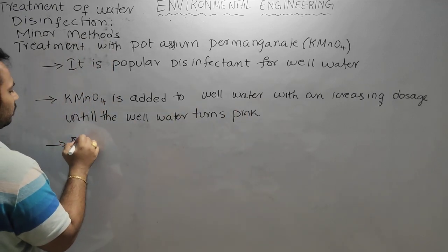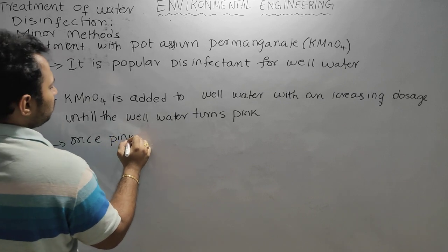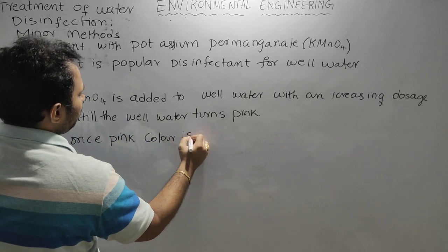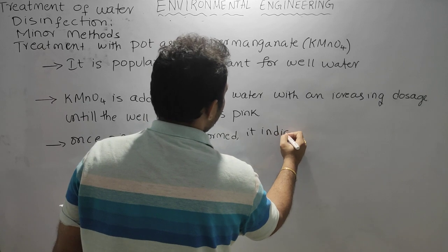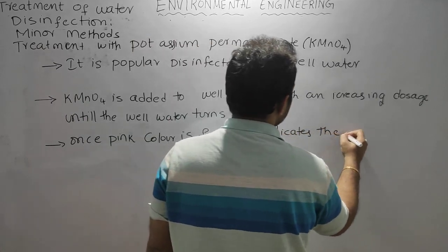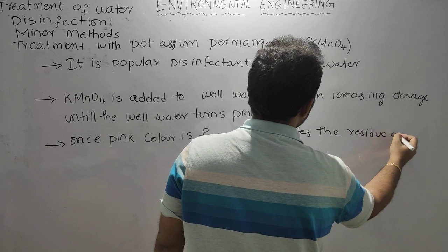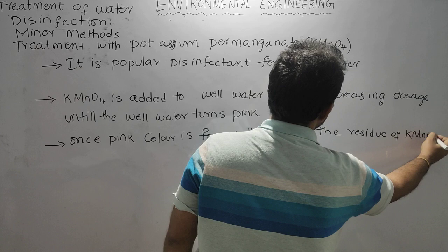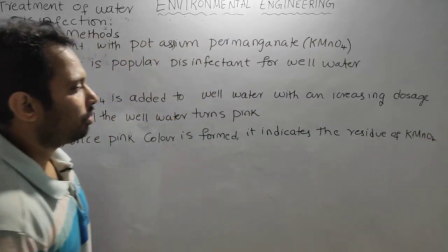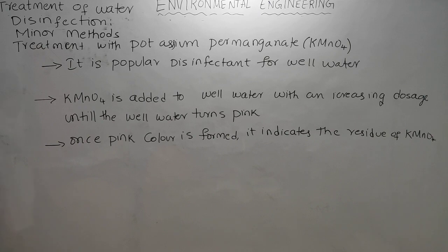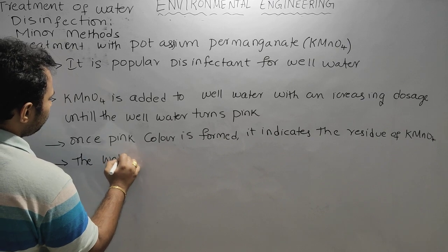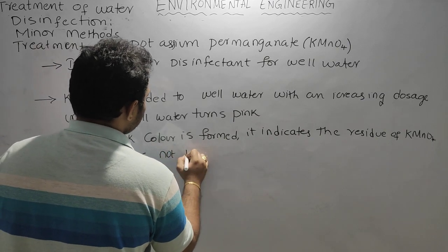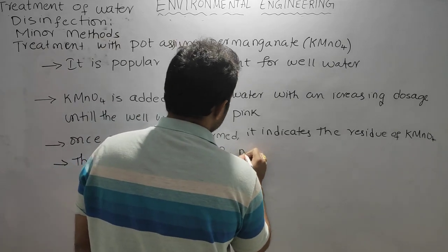Once pink color is formed, it indicates the residue of KMnO4, and the water is not used for the next 48 hours.